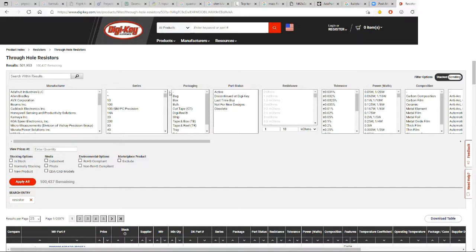And let's see, I guess we could select active power, and there are a couple of other things. One thing here is power in watts, the amount of power that these resistors can handle. If you choose something that's 0.05 watts, it's going to be super tiny, and it's not the scale that you're working at. You should go up to something like half a watt, that's good. Quarter watt is good. I guess let's do quarter watt.